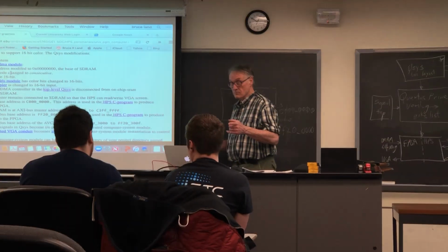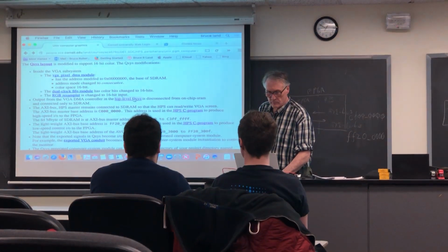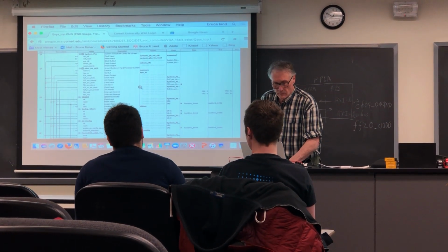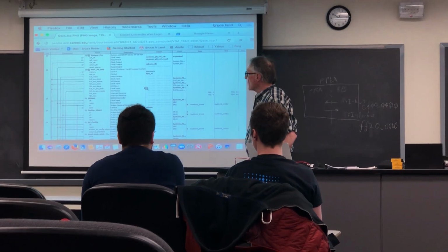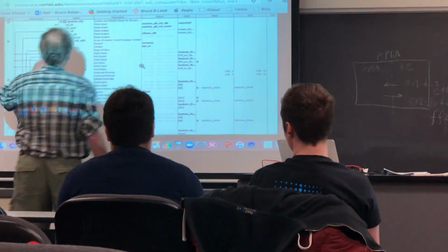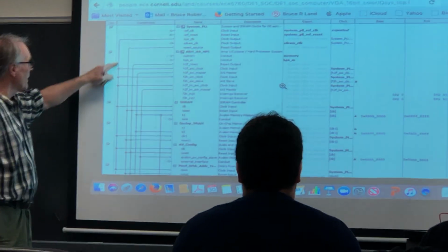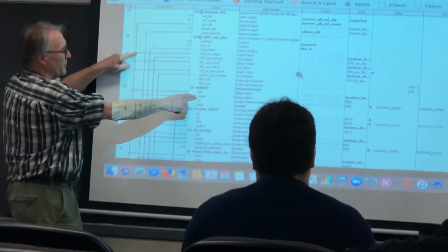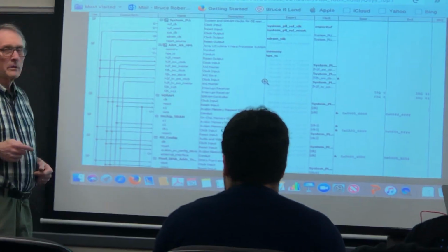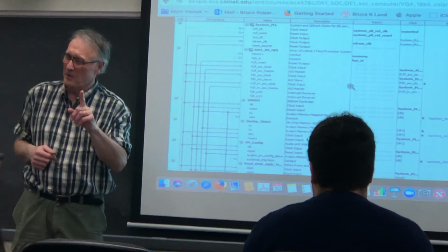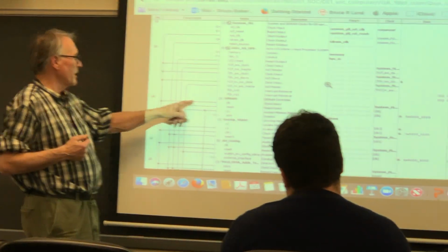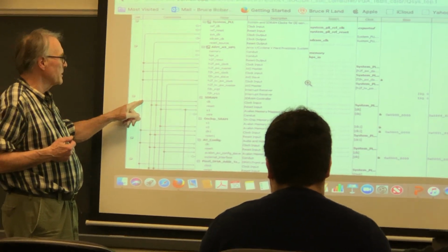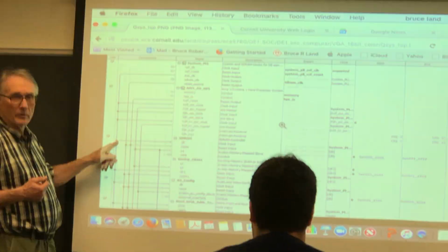Okay, so you open up the Qsys layout again? Sure. Okay, so there's this big section on the far left side where it shows signals being connected to other signals. What's actually going on there? So to output the system clock to a module, you look at the SDRAM clock, and if you were to drag out a fresh SDRAM module, you can't do that because there's only one physical SDRAM. But if you dragged out a fresh module, there would be no dot there, and you have to click on this intersection to give the SDRAM a clock input.